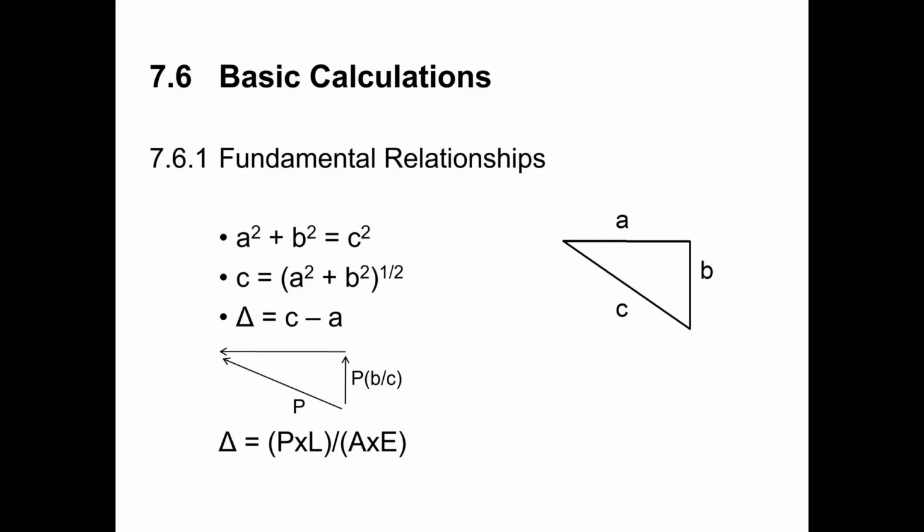And so instead of going through all of that process, they found it easier just to tension in the straight position and then to push the strands down into the draped position. So it really just depends on how the bed is set up as to which method is most economical.